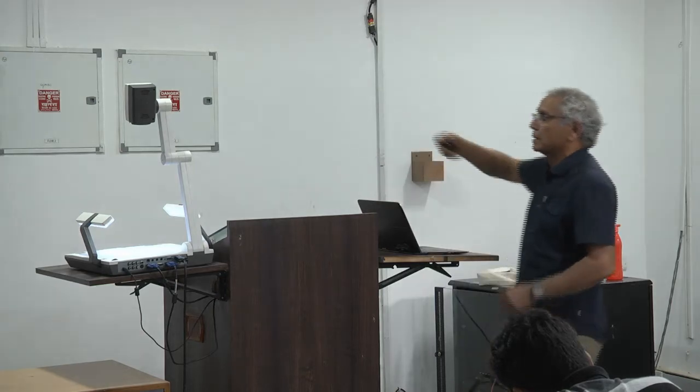I'll show you a figure of the critical resolved shear stress. Hard orientation, the pyramidal slip, called c plus a. Slip must occur for plastic deformation. And these are the soft orientations: the basal and the prism slip planes are the soft orientations, with easy slip activation.